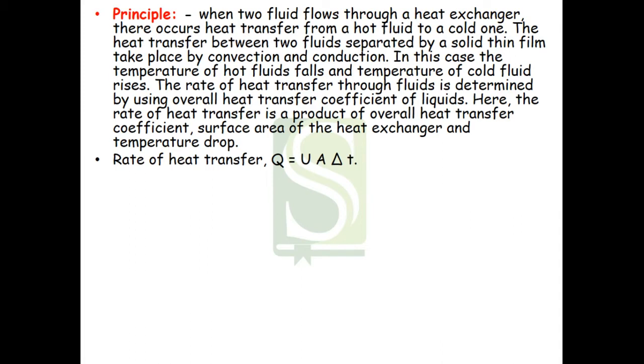The heat transfer between two fluids separated by a solid thin film takes place by convection and conduction. In this case, the temperature of the hot fluid falls and the temperature of the cold fluid increases. So the rate of heat transfer through fluids is determined by using the overall heat transfer coefficient of liquids. Here the rate of heat transfer is a product of the overall heat transfer coefficient, the surface area of this heat exchanger, and the temperature drop.